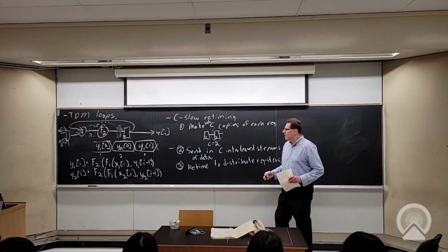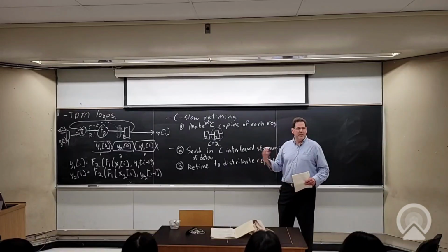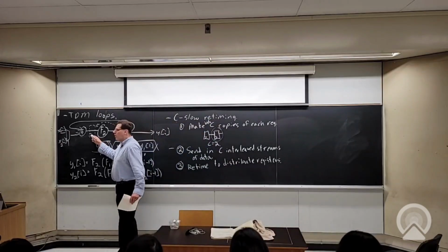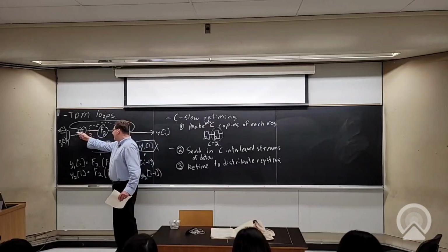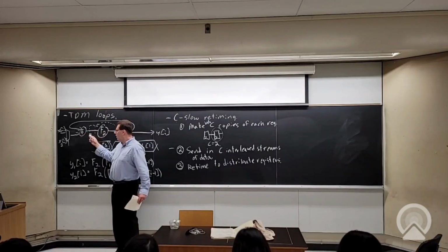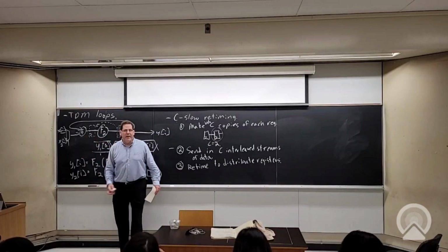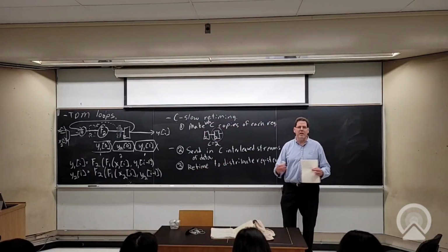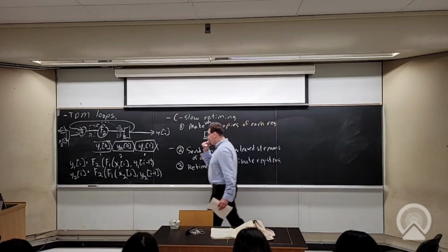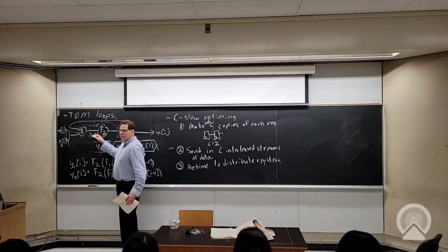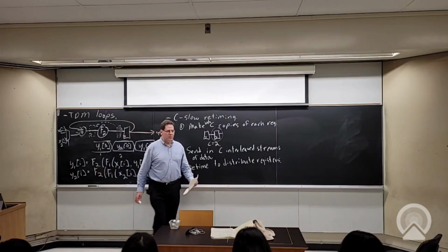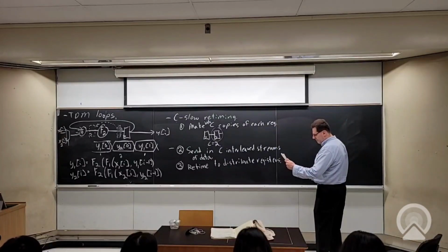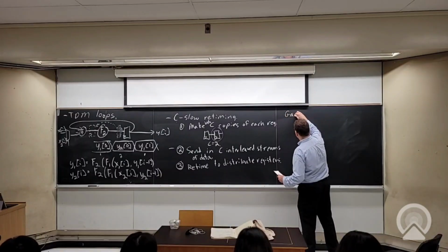So you're right. Another way you can match this thing is too slow: make many copies of it. The nice thing about C-slow retiming is it's relatively low cost, right? So let's say this is a lot of logic. I didn't duplicate all that logic. I just stuck another bank of registers in. And particularly in FPGAs, registers are pretty cheap because they've pre-built registers in many, many places. So until you get quite register rich, you usually don't even notice much difference in terms of device utilization. There's a certain point at which it hurts, but it is more efficient than just duplicating the unit.